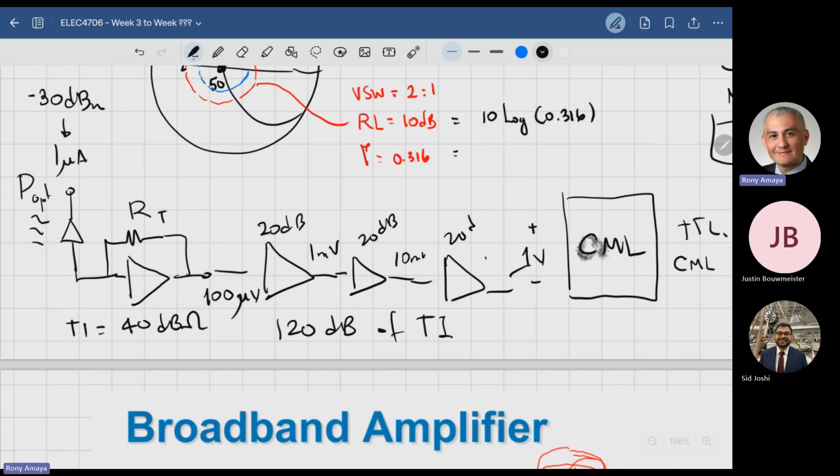So ideally, I wouldn't even need any equalization if I was to find a magical way to actually put a Bessel-Thomson function in each one of those four. No equalization needed. I'll be good. Well, the channel still has its own thing, but you can do a channel equalization and all the other stuff. So you have the group delay issues to deal with the channel, and then you have the group delay and all this other stuff happening with the electronics inside the channel.